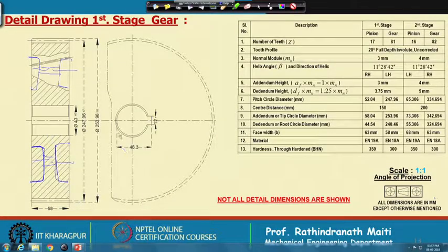And importantly, this key groove will be made by slotting, that means it will be through from this side to this side, and we have to mention from the bottom to the top of this, but this we may not need tolerances, because there will be some clearances. So, whatever the depth of cut is suggested, say T2 on the chart, if you look into the key table, add that with the shaft diameter and put that value here, and this width is 12, that of course needs some tolerances.